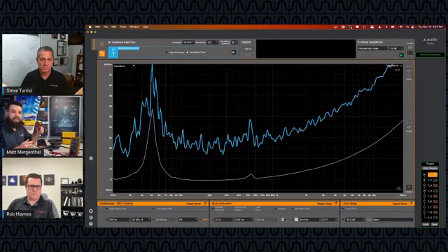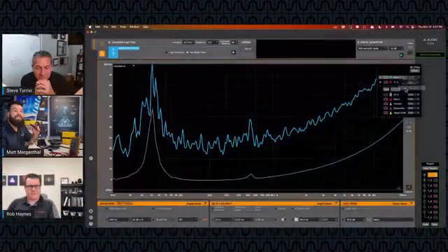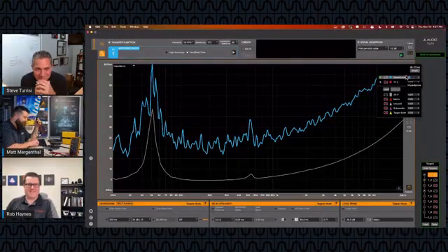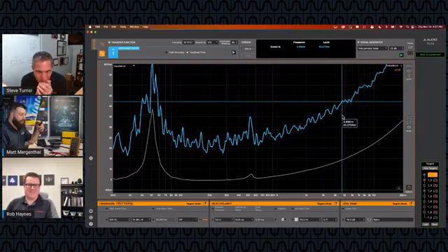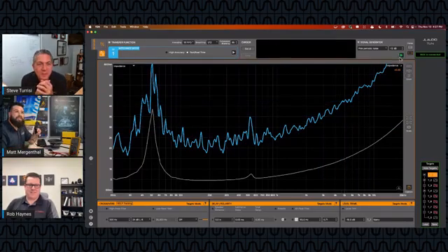Okay. So what I want to do now is I want to actually take the alligator probes, and we're going to calibrate the measurement, and that basically allows us to position the data on screen where it's totally accurate. And I made a mistake already because I've already calibrated it and I didn't reset it. So we'll pretend that it was not calibrated. Whoops. And we will start over. So what I'm going to do here is I'm going to pause the signal generator, and I'm going to connect my resistor to these probes.